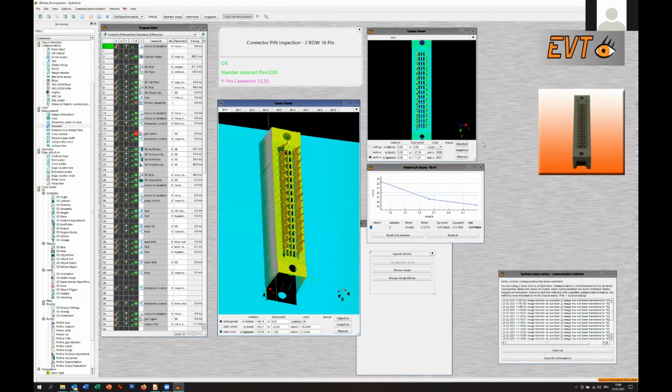And here you see an example of how to do inspection and measurement on pins, any kind of pin header. This is a total program. It's easily made. Of course, we have discrete inspection. This works on any kind of oriented multiple objects like grids, like BGAs, or if you have to count anything which is oriented in a grid, it doesn't have to be always the same n by m. You could also exclude some stuff. It's really nice. So you simply open it up and you see it.